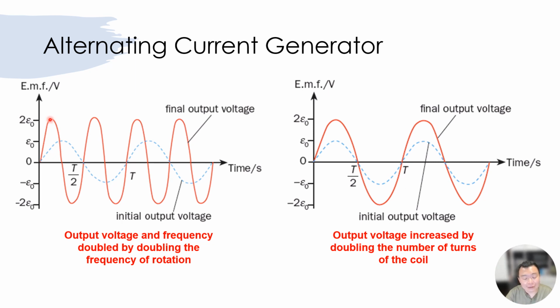Right. Now, one more thing is about the time axis, because we now turn the coil faster at double the speed. Therefore, you notice that the number of cycles has now increased, has now doubled in fact. Previously, when we turn the coil at a normal speed, you can only see one cycle here and a second complete revolution here. So two complete cycles over here.